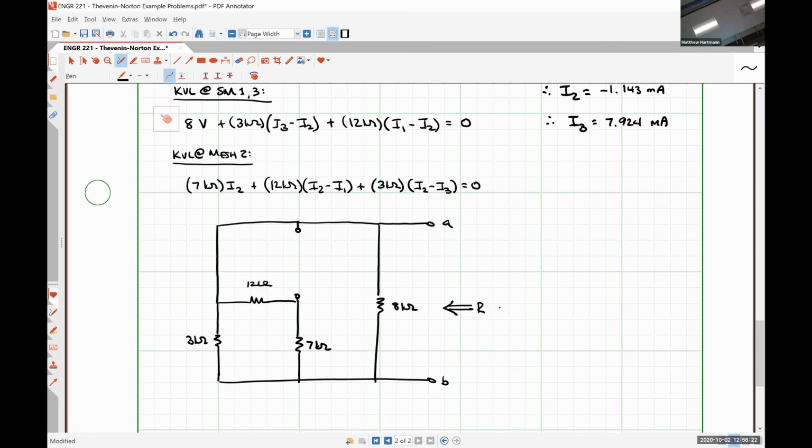So Norton's theorem is effectively the source transformation of Thevenin's theorem. So the Thevenin resistance and the Norton resistance are literally representative of the exact same quantity, and they're found in the exact same way by looking at a dead electrical network and measuring the equivalent resistance seen between the terminals. So I'm going to call this R Thevenin.